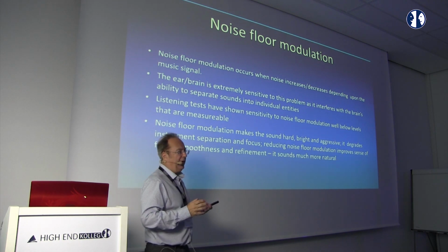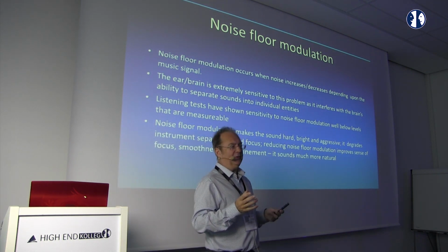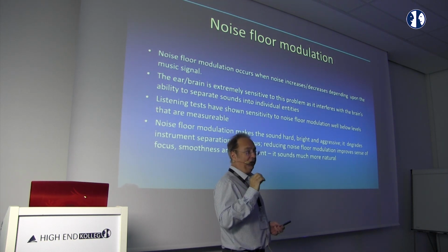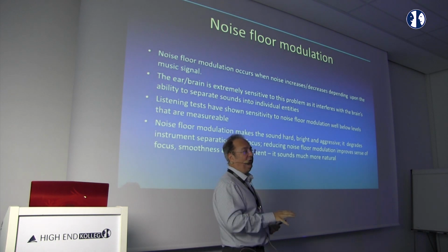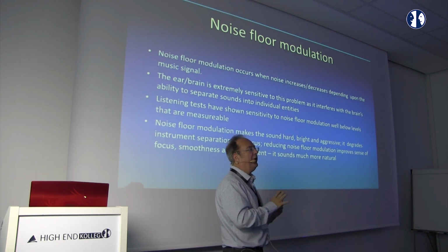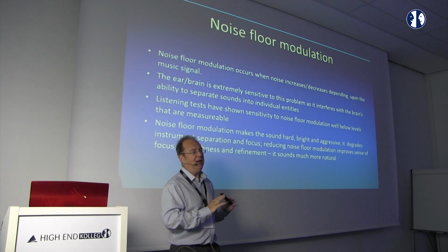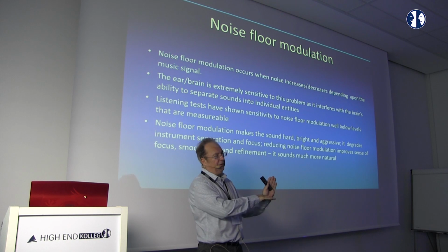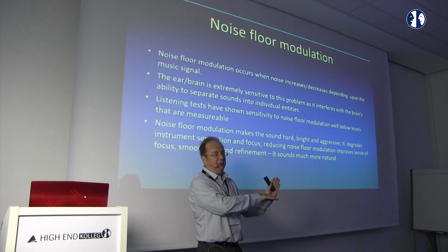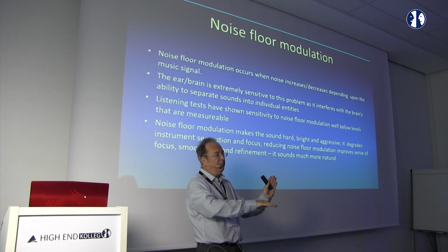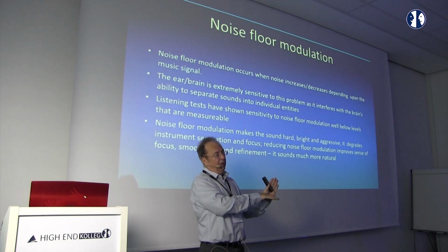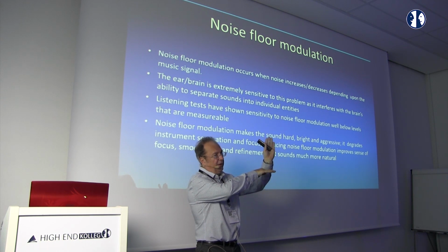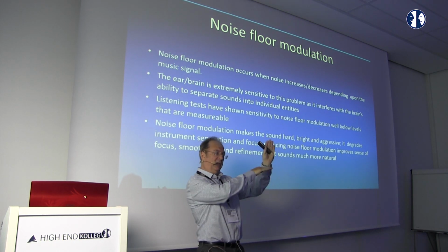Noise floor modulation. If anybody's attended any of my talks or watched me on Headfire or anything, noise floor modulation is something that I go on a lot about. And it's actually very crucial to performance. What is noise floor modulation? If you take a very small signal, say at minus 60 dB, and measure the noise floor, you'll see the noise at conventional DACs between minus 160 to, say, maybe minus 180 dB. When the signal increases, the noise itself increases. So the noise floor pumps up and down with the signal.